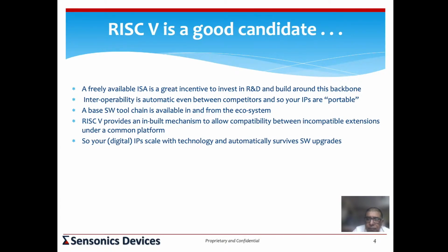But suffice it to know that RISC-V has a mechanism which they call the control and status registers, CSRs, and there's a bunch of well-defined CSRs. Those CSRs, the specific ones that you might want to look at, are the ones called the machine ISA, MISA, and the machine vendor ID, called MVENDORID, and the machine architecture ID, called MARCHID, and the machine implementation ID, called MIMPID. These four CSRs can be set up suitably so that